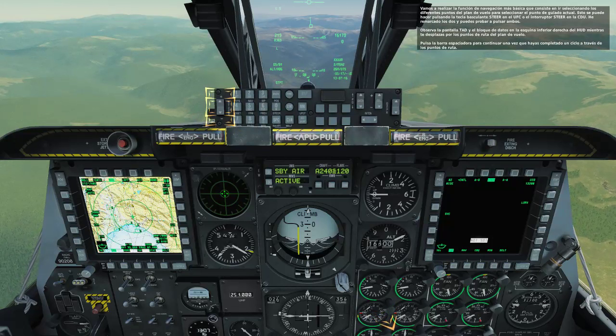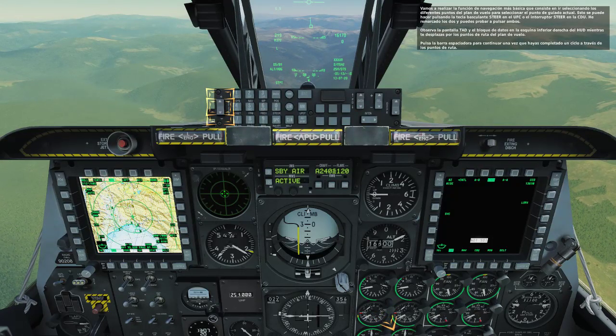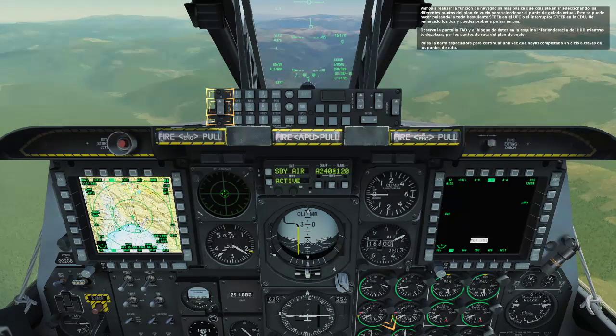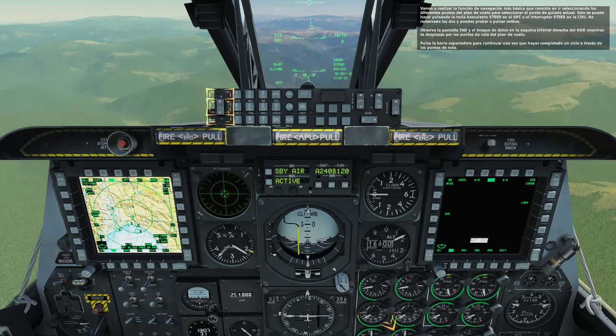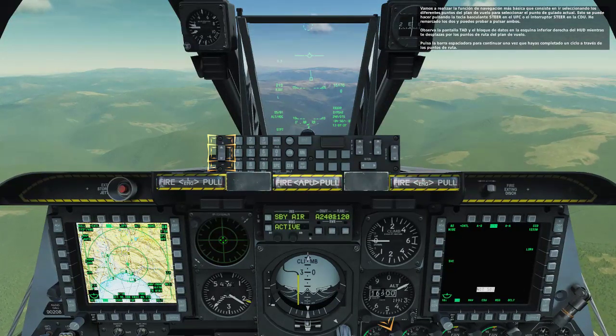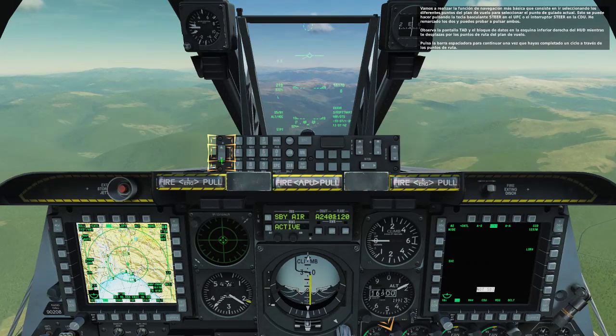Let's try performing the most basic navigation function of cycling through the flight plan waypoints to select the current steer point. This can be done either by pressing the steer rocker key on the UFC or the steer switch on the CDU. I've highlighted both and you can try pressing both. Watch the TAD display in the data block in the bottom right corner of the HUD as you cycle through the flight plan waypoints. Press the spacebar key to proceed once you cycle through the waypoints.